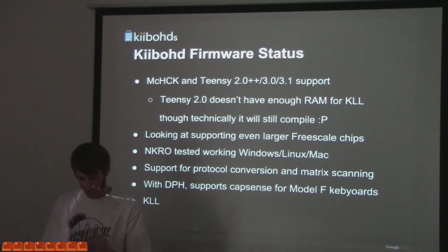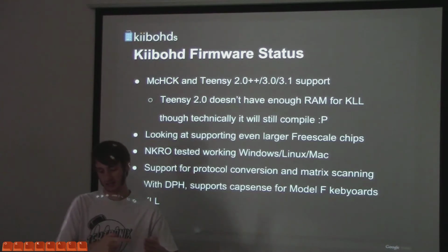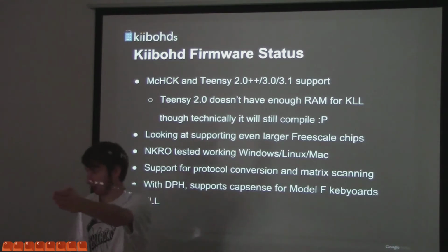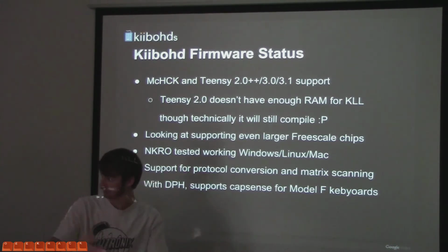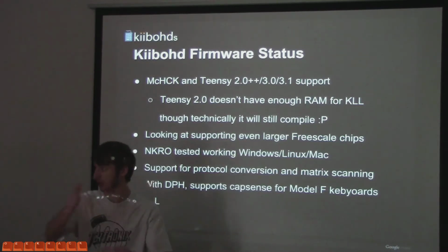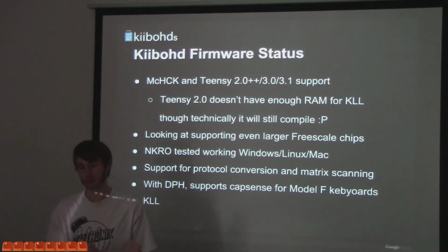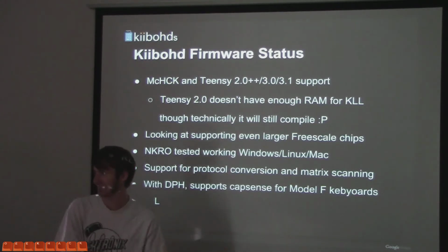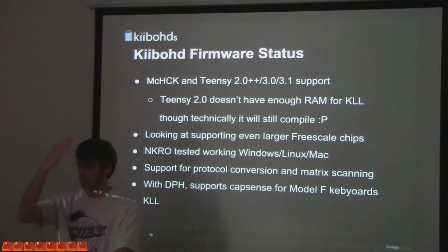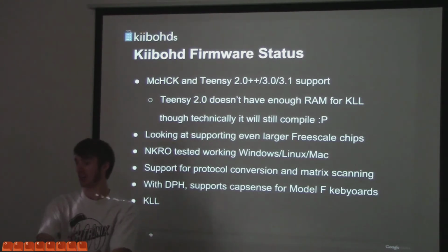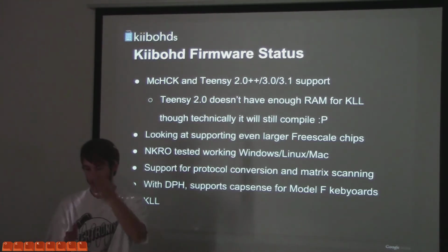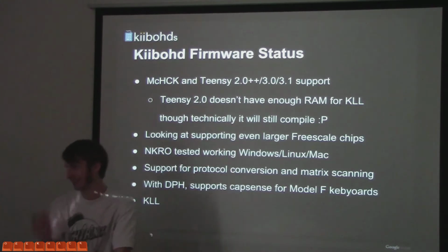So what they do is they assign a matrix of switches, and they scan them. They'll power a row of switches, and then sense each of those columns. So columns versus rows, and you'd be strobing these keys. Depending on what kind of switch you're using, capacitive sense or electrical is the easiest to think of, you have two contacts, you sense if it's there, and you're going scan, scan, scan, scan, scan, really as fast as possible.